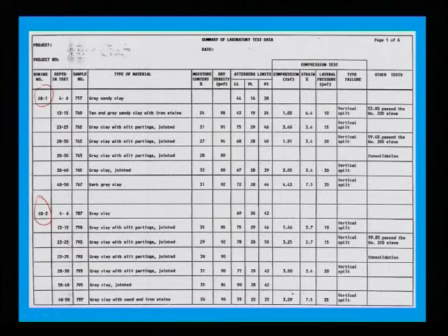Depth 4 to 6 meter you have taken sample, sample number you always provide. If it is number 1, you write number 1, 2, 3, 4, 5, 6 like this, sample number to be there, here sample number is there. At what depth you collect your undisturbed sample? Say at depth of 4 to 6 feet you collect undisturbed sample, 13 to 15 feet you collect undisturbed sample, this has to be clearly mentioned.